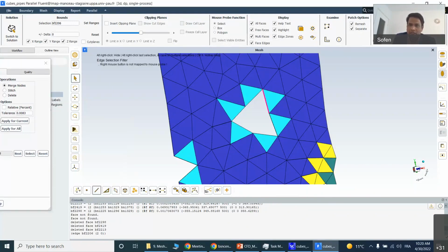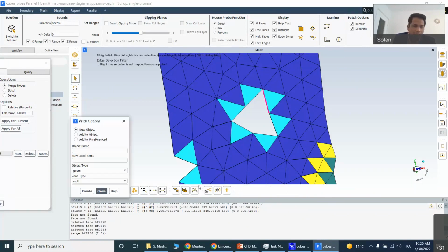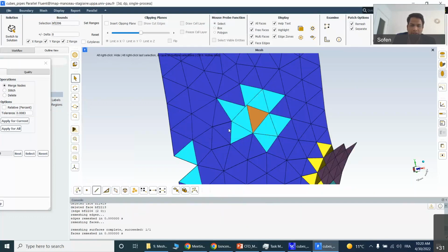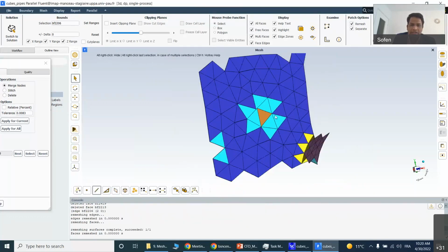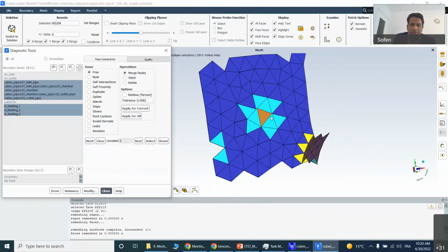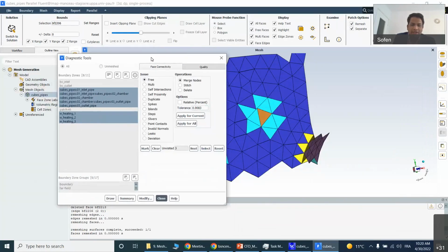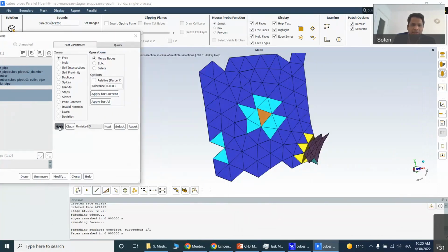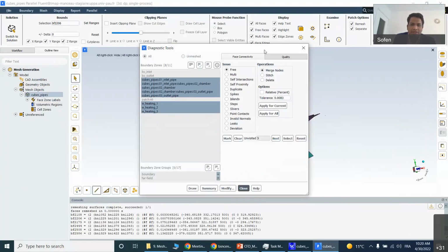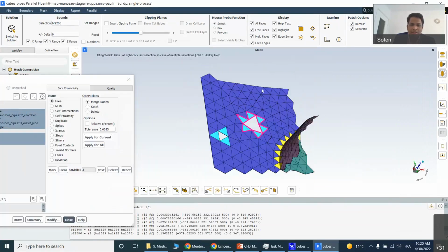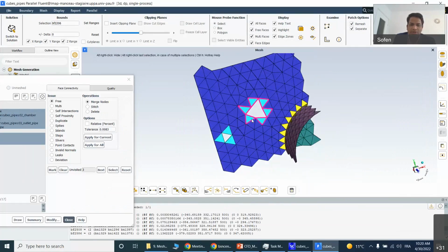Just a second, I just separate each option. Create, geometry, create. Yes, you can see something is created, right? But it is still showing free faces because a new geometric object is created. To avoid that, next go and mark; it is showing 9 free faces. So again there are a number of free faces. How to stitch those free faces? I can also go and simply delete them.